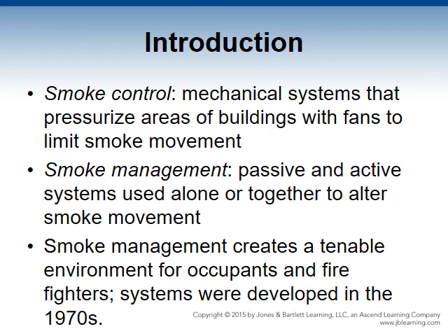The life safety objective of a smoke control and management system is to provide a tenable environment in the areas next to the fire area for building occupants and firefighters, and also to confine the smoke to the area of origin. This allows occupants to evacuate safely. This also allows firefighter relocation within a structure or management of the smoke intensity to facilitate fire department operations.